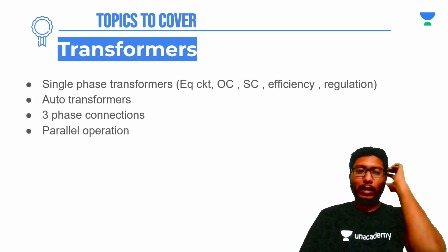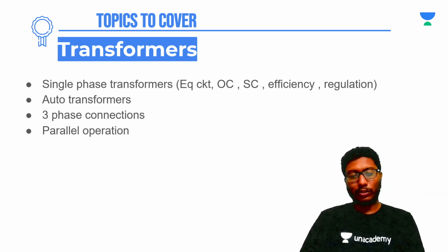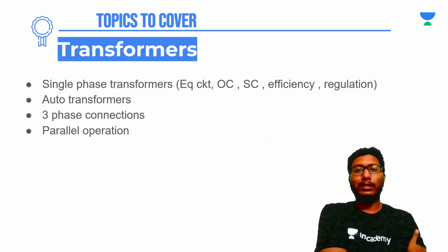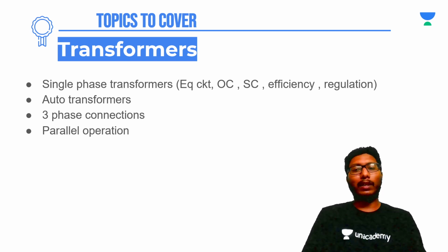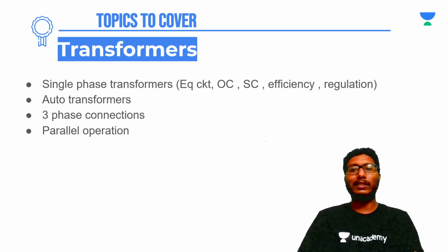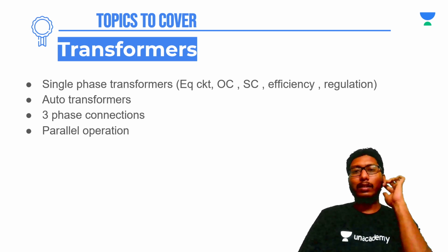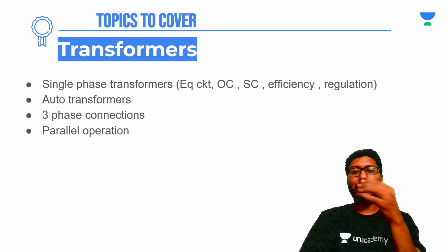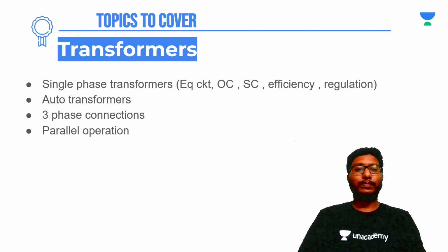So as I have told you, in series magnetic circuits we'll use this KVL type of approach. In the parallel case, what we do is we make reluctance times flux equal, which is equivalent to voltage here. Since in parallel circuits, the voltage across n number of parallel paths is the same, here in the same way, the flux times reluctance will be the same. So that is one thing.